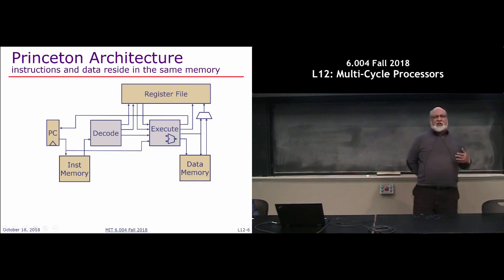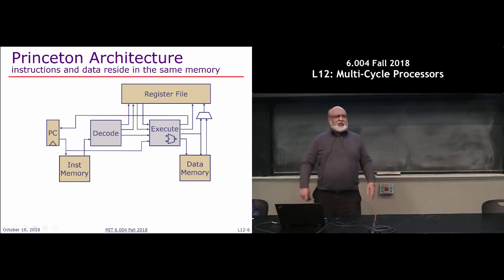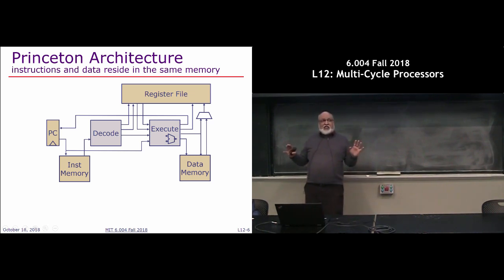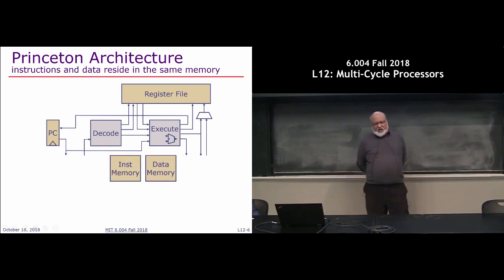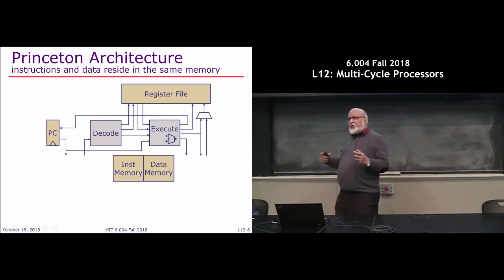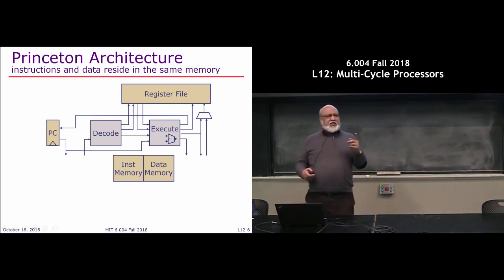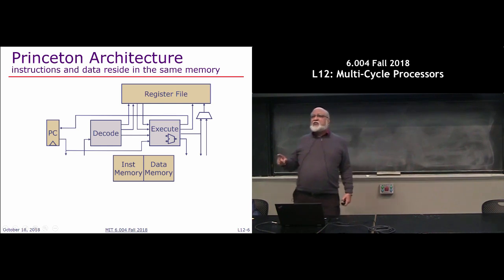You better have a very, very good reason where you want to do surgery on a program and produce a new program from it. So normally we like to keep these two separate, but I want to make a point about hardware today. So suppose they are in the same memory. If they're like this, that instruction memory and data memory is the same box, first thing that immediately comes to my mind is, now we can no longer do memory instructions in one cycle.